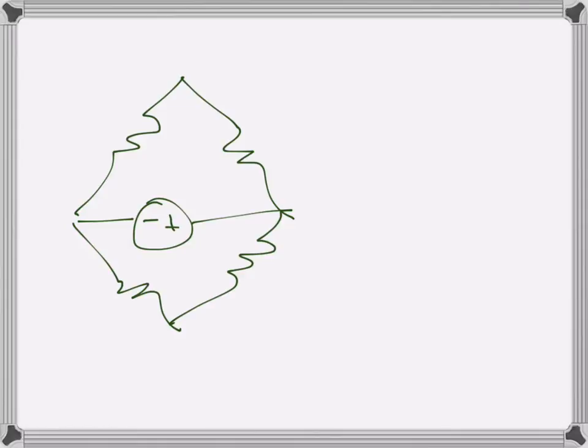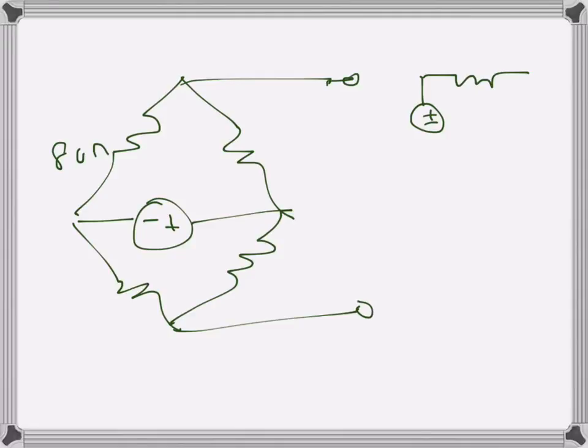What we will do now is find the Thevenin's voltage. We will replace the entire circuit by just one voltage source and one line resistance, which we already know, so we just want to find the Thevenin's voltage, the open circuit voltage there. So 10 ohms there, 90 ohms there, and then 40 volts there. With this arrangement, these two are open circuit, so we want to find the voltage difference from this point to this point.